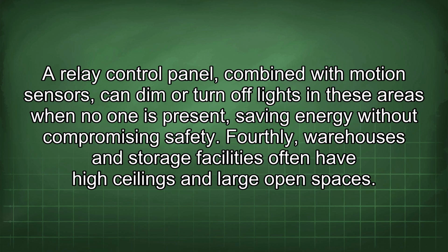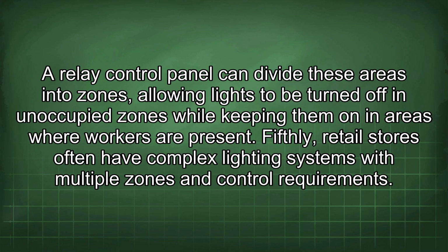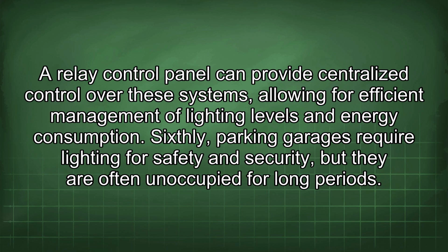Fourthly, warehouses and storage facilities often have high ceilings and large open spaces. A relay control panel can divide these areas into zones, allowing lights to be turned off in unoccupied zones while keeping them on in areas where workers are present. Fifthly, retail stores often have complex lighting systems with multiple zones and control requirements. A relay control panel can provide centralized control over these systems, allowing for efficient management of lighting levels and energy consumption. Sixthly, parking garages require lighting for safety and security, but they are often unoccupied for long periods.